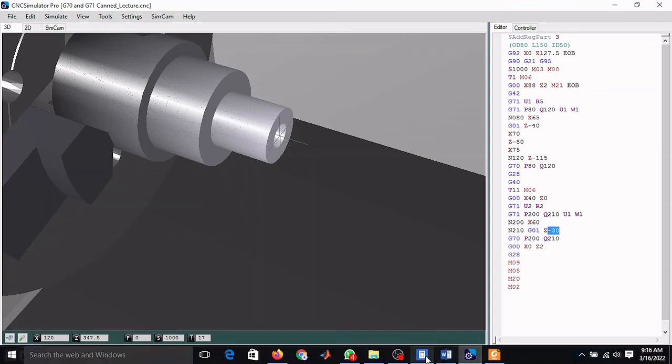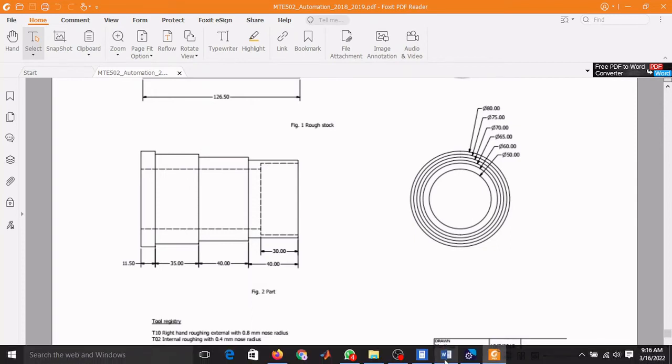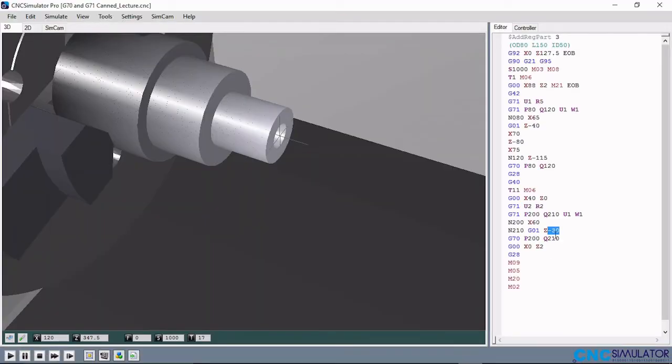So that is what is happening here. So this depth of 30 is to bore this diameter inward to 60 mm from 50. So that is what is happening on this line. So the diameter should go to 60, to a depth of minus 30 using the linear interpolation.